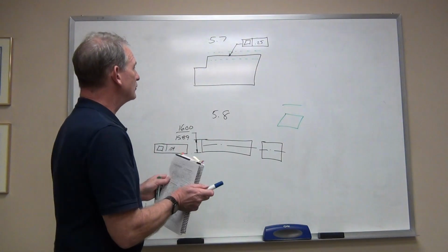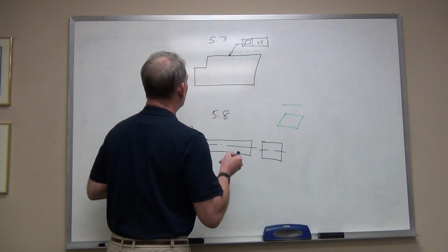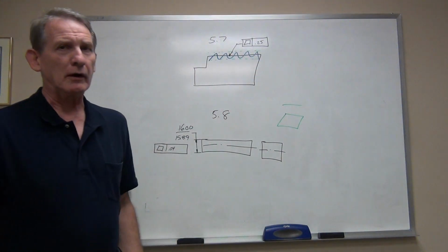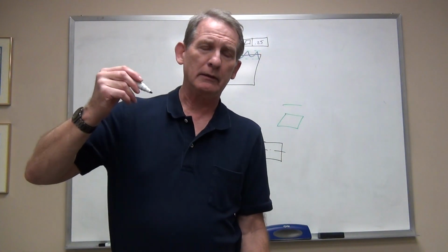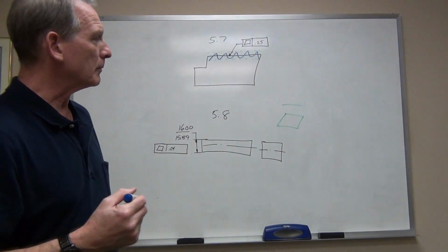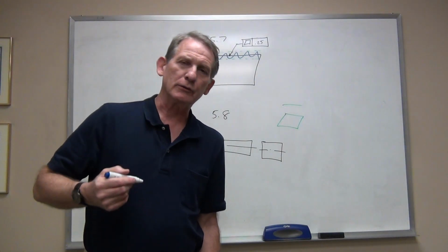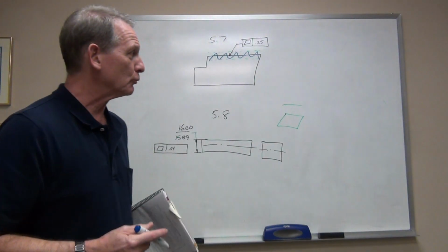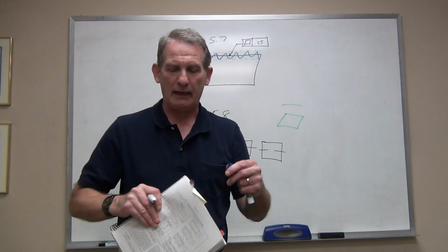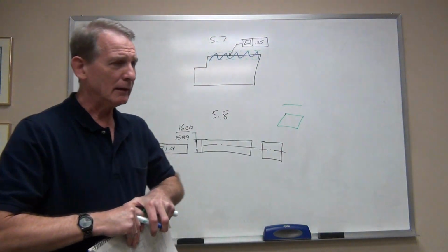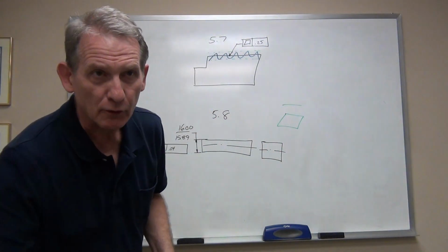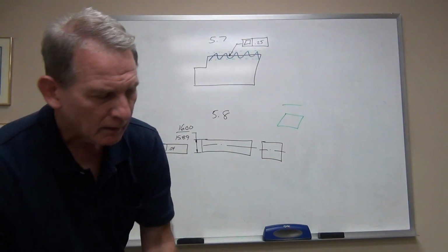So again, you can get sort of wacky, and as far as the requirement for flatness, the requirement is met. Okay, so that's something you always want to think about, is what can happen within a tolerance zone of that size. But here again, we've seen the two parallel planes as another form of tolerance zone.